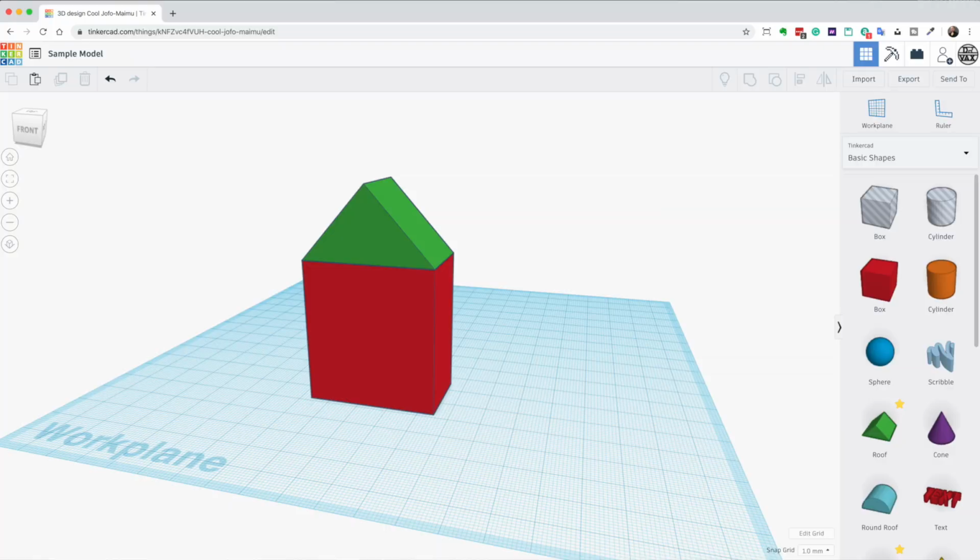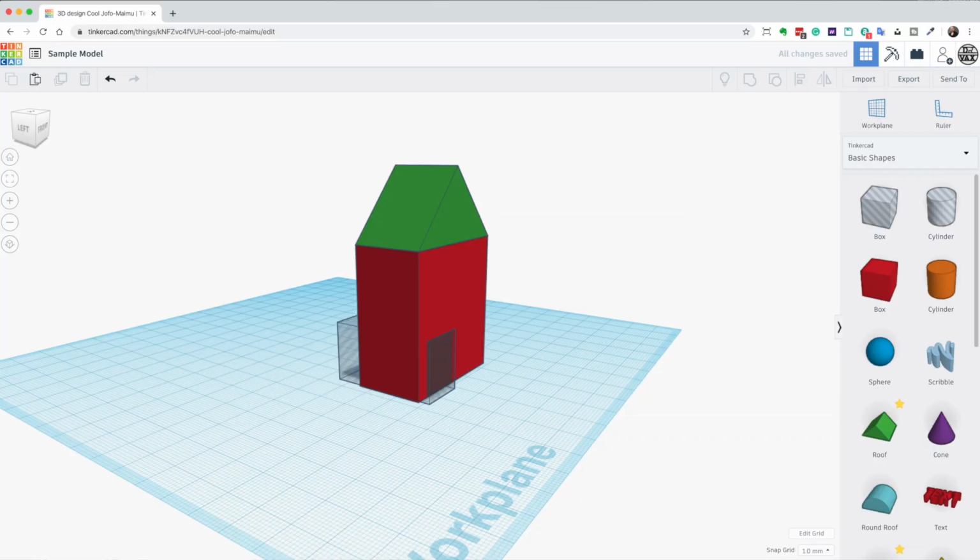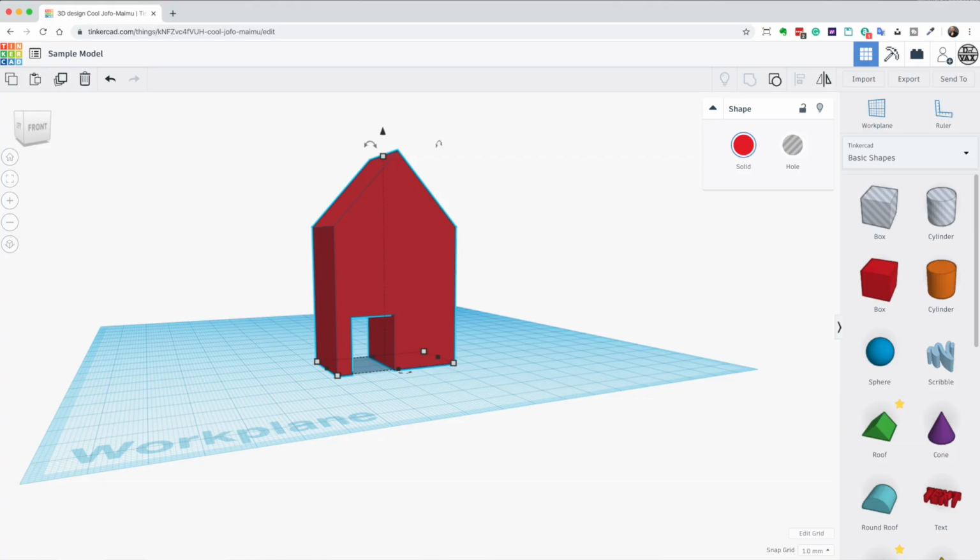But basically you stack three-dimensional objects, cubes and cylinders and pyramids together to create objects. You can define an object as a solid or a hole. If it's a hole, when you stack it together, it makes a cut into an object. But Tinkercad's drawing capabilities, the ability to draw something from scratch, not a predefined object, are very, very limited. There's an easy way to extend those capabilities, and that's to use SVG, Scaled Vector Graphic Files. But you need a way to create those.